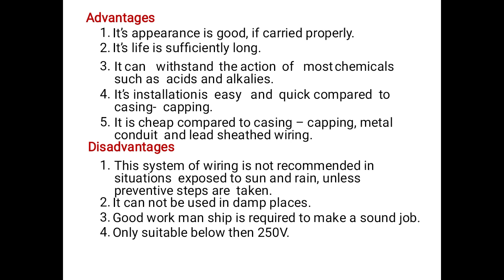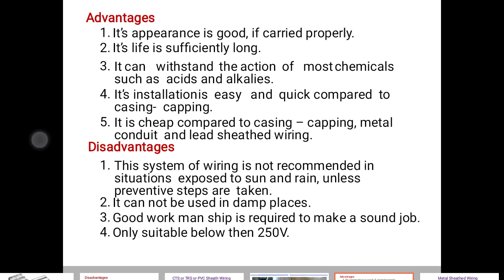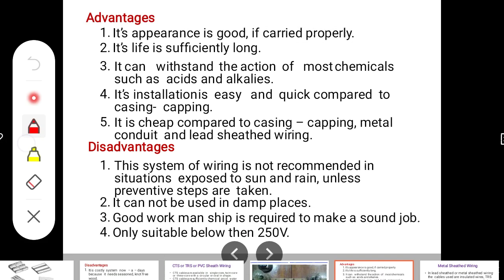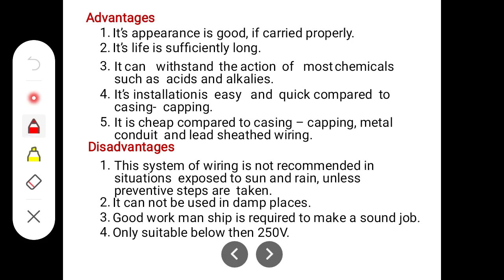This system of wiring is not recommended for some places. These are the disadvantages. Sun and rain must be prevented, so it cannot be used for damp places. Good workmanship is required to make a sound job. Whatever the system, skilled persons are required, that's the main disadvantage. It is only suitable for 250 volts. For higher voltages, we cannot use this CTS wiring.